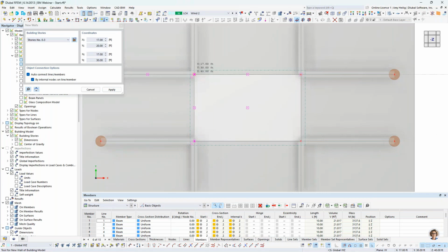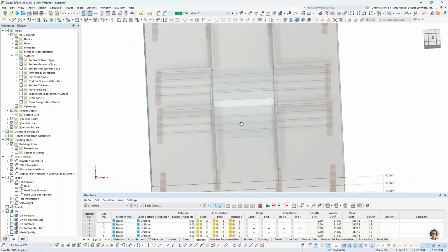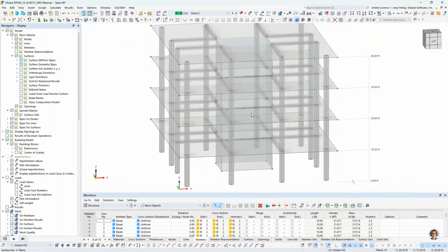And I'll go ahead and close the loop here. I can right click to exit twice, and now we have our shear walls modeled. The final modeling step, though, is we probably want to add in openings here to the shear wall, maybe for some elevator, stairs, whatever it may be.